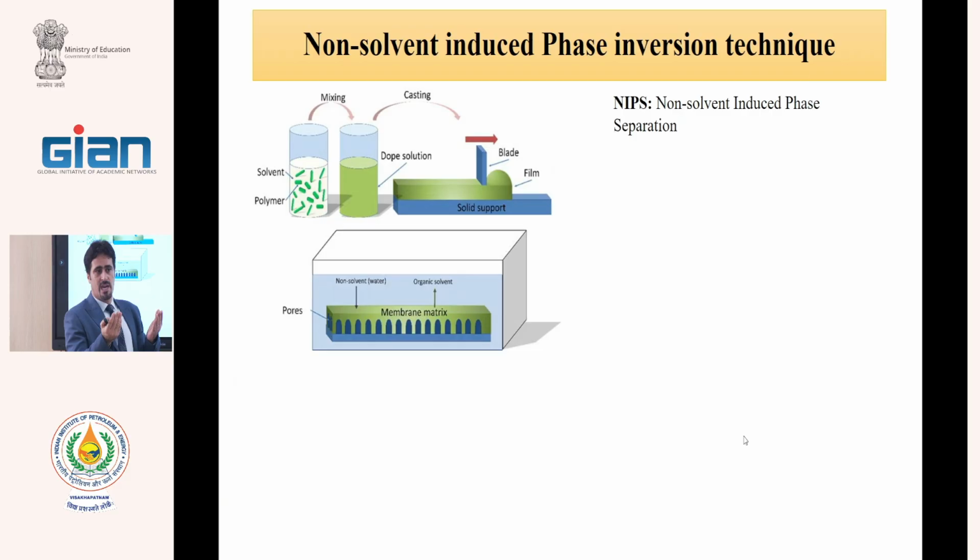During the fabrication we see that there are some visible pores in the film, and this is due to the gases in the dope solution. Therefore, after complete dissolving, we keep the solution 1 day again without stirring for degassing, or use an oven for degassing.